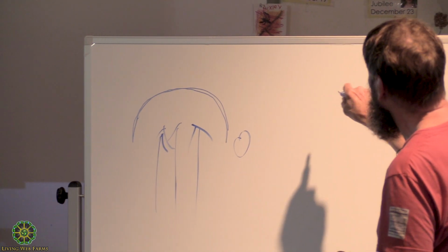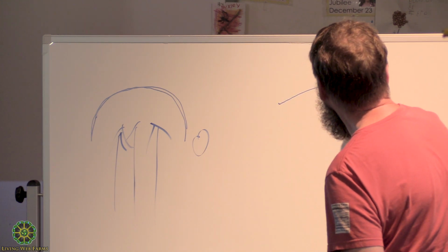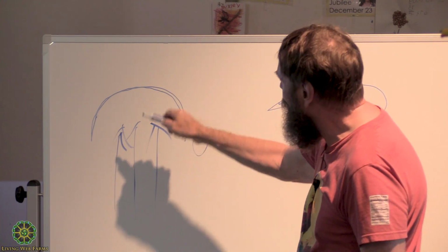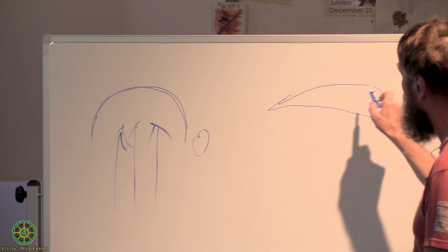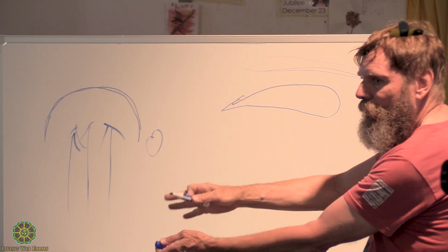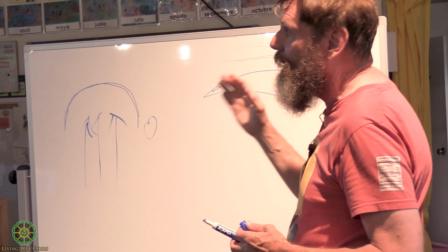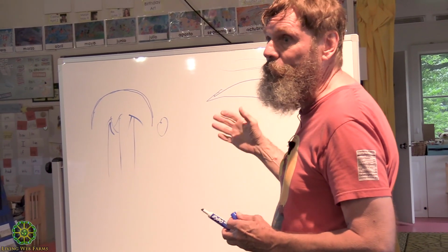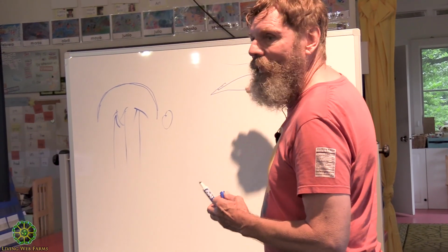Airfoil, looking from the end of the blade, if you held the blade out and looked down the thing, an airfoil, I'm just gonna sort of give the wind's 10 miles an hour, it can only turn it at that speed. It cannot make it any faster. As the wind goes over the surface of a blade like this, it actually creates a suction. So the blade can spin faster than the wind is going. And if you use the right design parameters, you can get what they call a much improved tip-speed ratio. So a 6-to-1 tip-speed ratio is really good, and with a well-designed blade, that can happen.